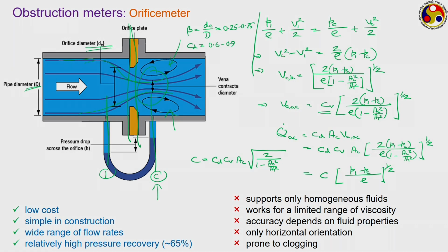The larger the flow velocity, the larger the Reynolds number, the vena contracta may appear further downstream of the orifice location, and therefore it is not a fixed location for which you can mount your manometer to get the pressure reading. So, while P1 can be at any fixed location, for PC we have to be a bit experienced to locate its appearing location properly.